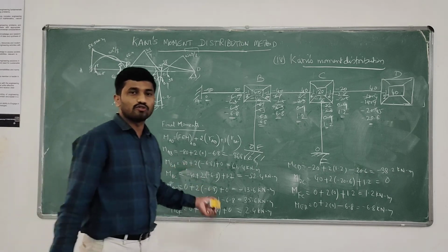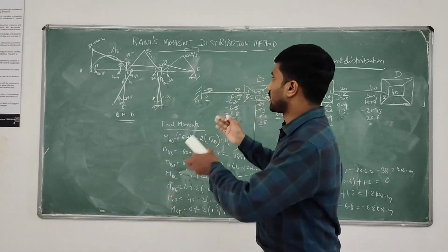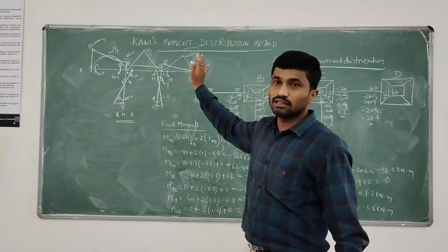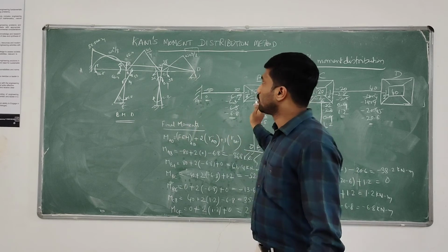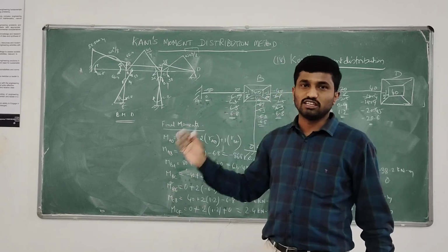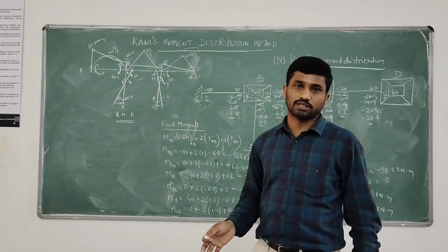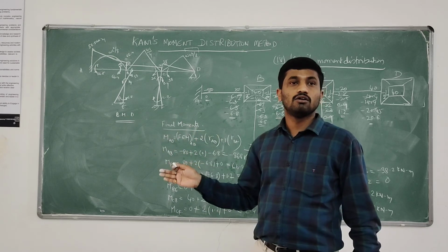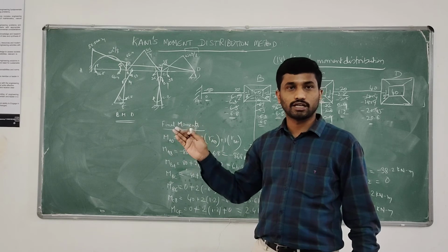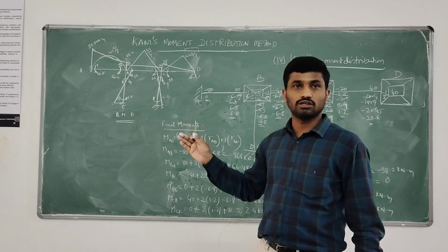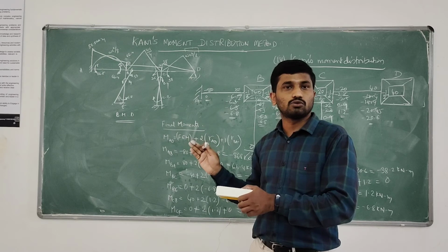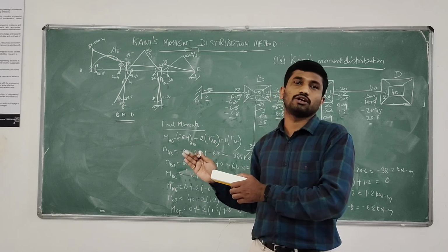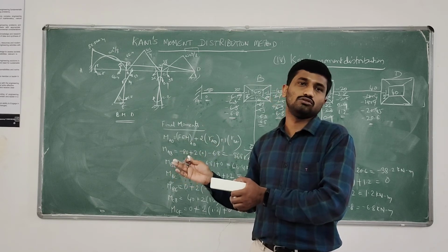So this is regarding bending moment diagram. So we are just imposing free bending moment diagram as well as final moments in one final bending moment diagram. This is the case regarding non-sway frame using Kani's method. So the very simple steps what we have followed in this particular method are: first we identified the kinematic indeterminacy. By that we got to know that the given frame is non-sway frame because we got only rotations as unknowns.